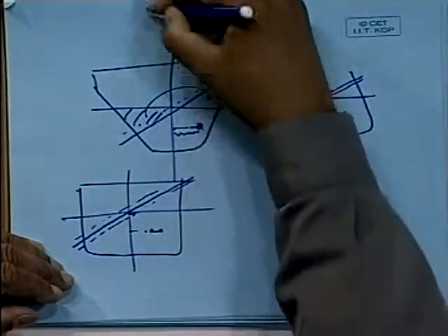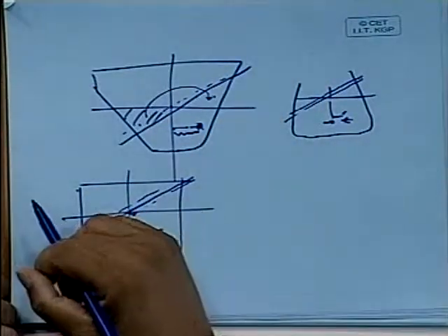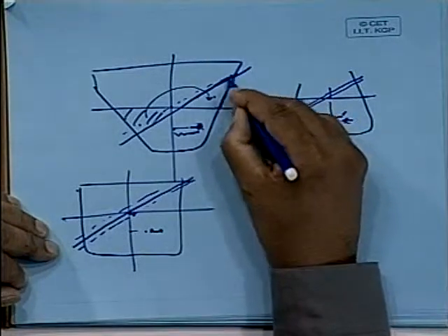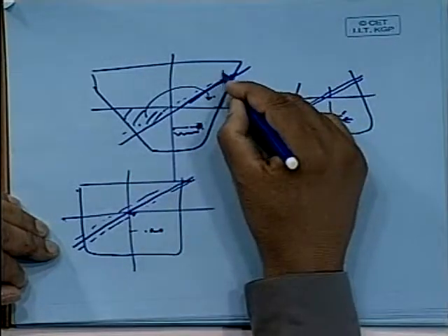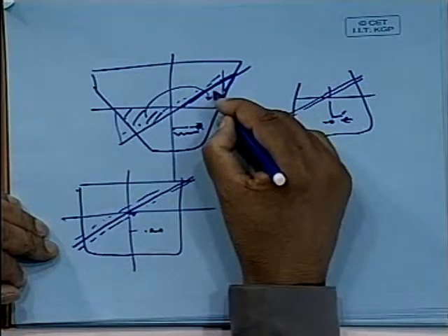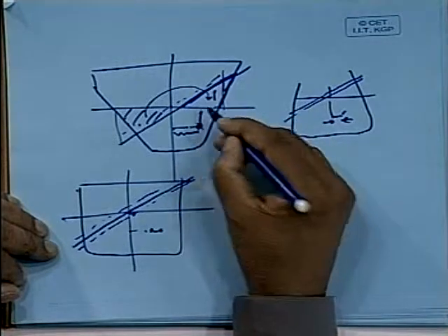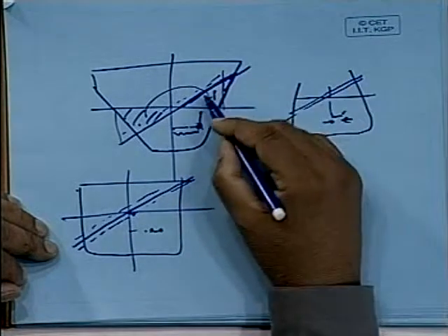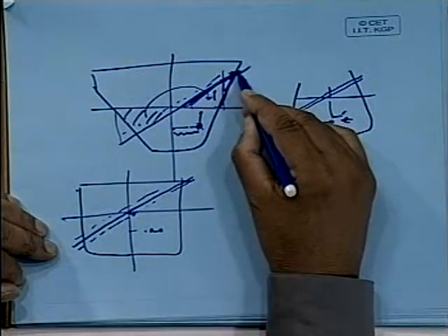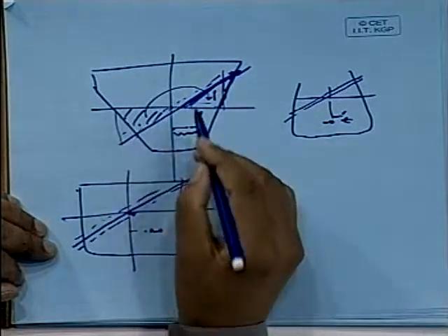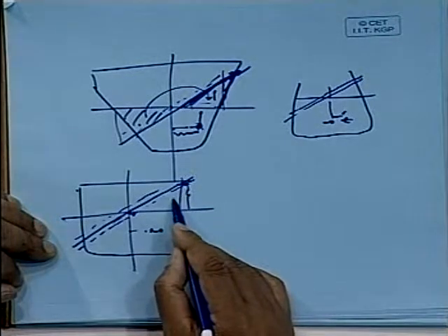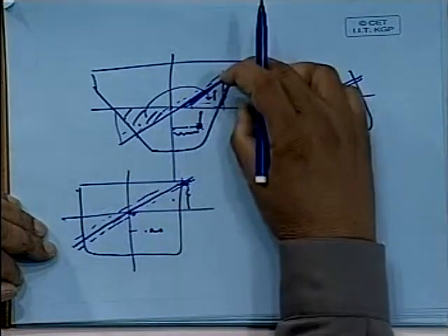If the shift of B increases, obviously, first of all, GZ will increase. The second thing is that this part is higher here than this. If you consider this way, because this part is above, the rise of G also is more, because there is more weight added on the top. This point is higher, this particular point, this much compared to this. So the weight is shifted, the center of gravity is shifted 2/3 of this height. Here it is 2/3 of this height.